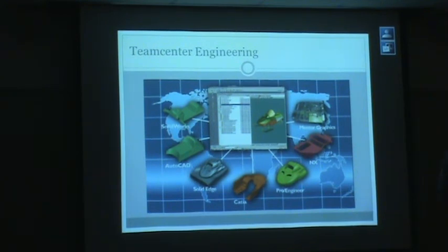If the part drawing is a drawing of something that is cast, it won't have draft angles and things like that on it. That part drawing, along with the part itself, will go over to the manufacturing space, and in the manufacturing space, they'll put draft angles and everything else to make it right. They'll tweak the drawings so that it is a cast representation of the part. And so one is saved in the product definition area, the other one is saved in the product production area. So, good question.